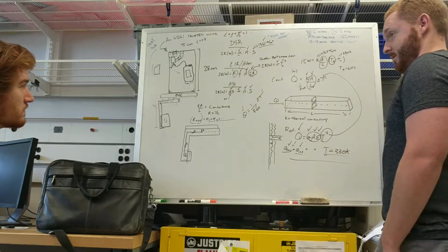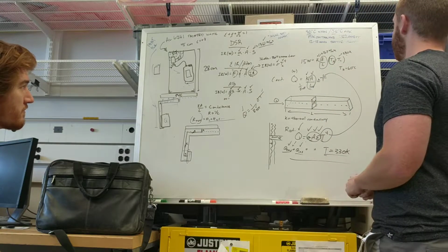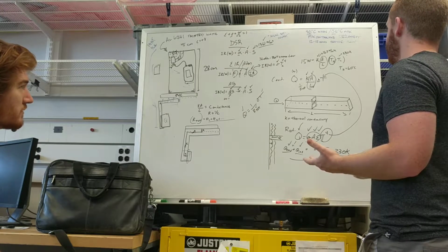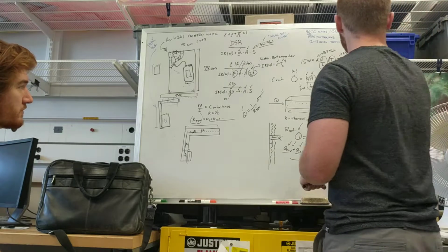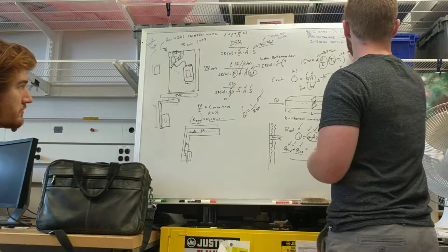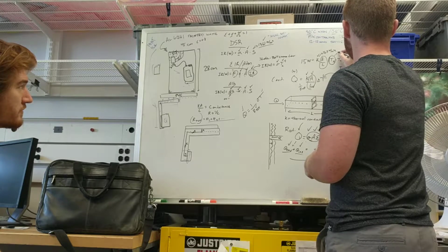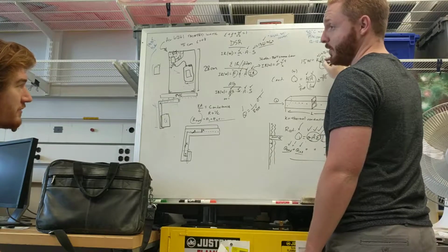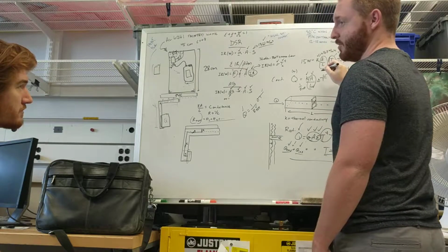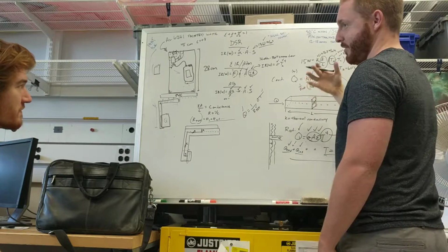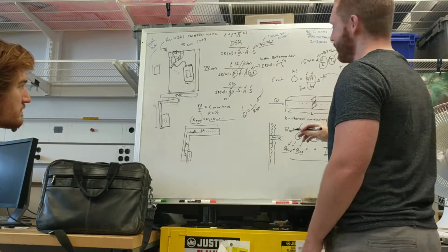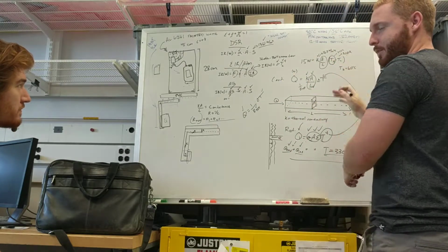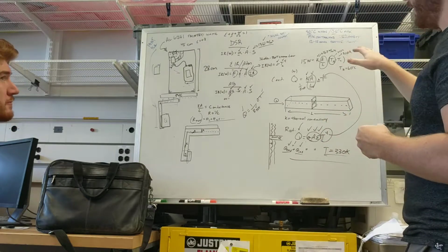The other thing you can do, if you really want to play around with this, is this: let's see, 50C is what? 323 Kelvin? Okay, so let's just say this came up to 300, and you know that you want this to be 323 as a maximum. Now you've already solved for that, and your unknown is your A over L. Now you can design something that meets the A over L. So you can plug in different information and manipulate it as you see fit, because you have more than enough information to do that.